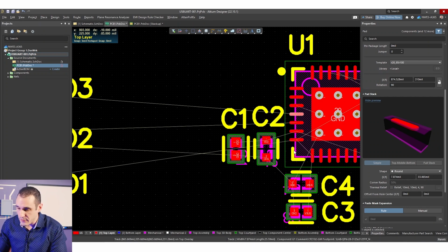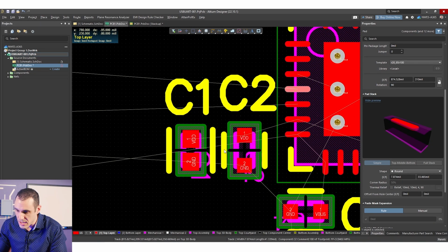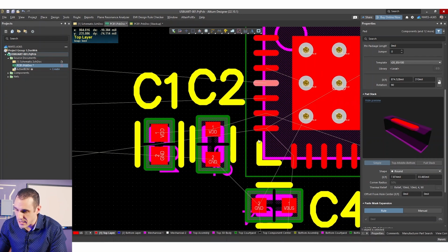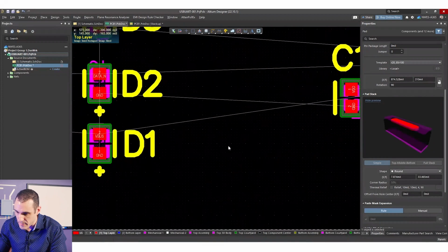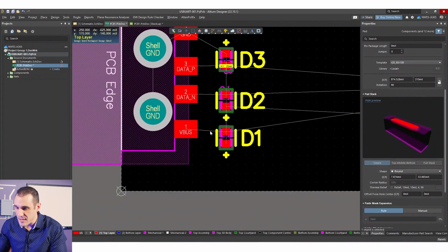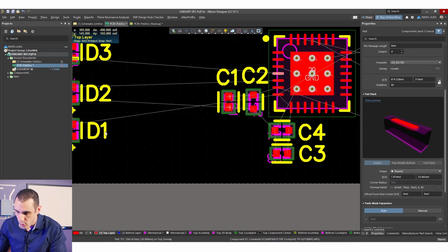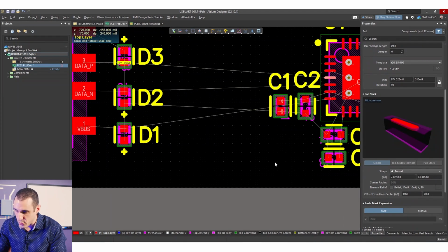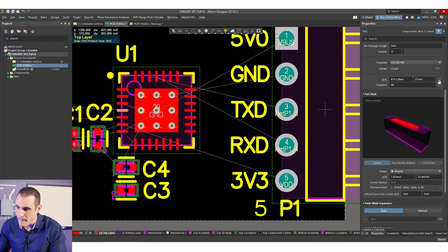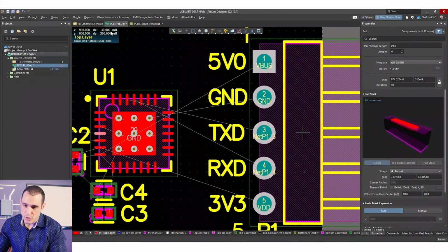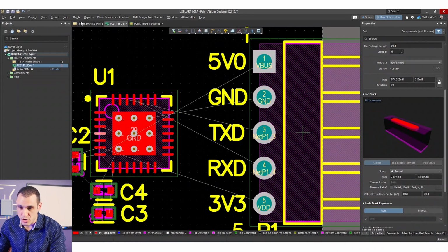And then to handle VDD, we can route those rails on the back layer, and we can do the same with VBus. We could route that on the back layer. However, given that VBus is actually down here on this part of the connector, we can just route a thick rail if we want to over to this region and make the connections here, and then route another thick rail on the backside up here to this edge. Probably, I think the optimal solution would actually be to switch these two nets.